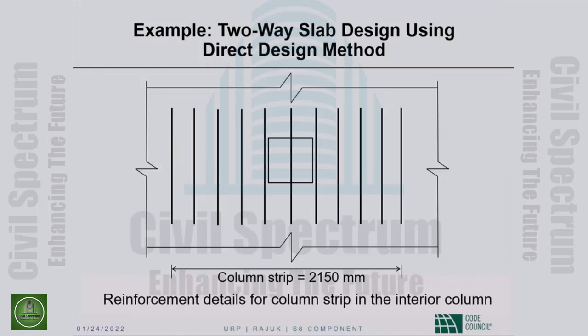Moving on. So in our country, slab design practice, we currently practice crank slab rebar. What rebar? Crank slab rebar. I don't know what that is. Main reinforcement is bent from bottom to top. Oh, in the slab. No, in the beam it has been used, but this is very uncommon. This is not used anymore.